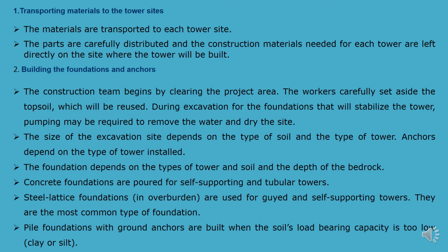The size of the excavation site depends on the type of soil and type of the tower, right? So size of excavation, right? So we cannot decide the sizes arbitrarily, but we have to design according to which type of soil is there and which type of tower is there, right? So according to that you have to decide the size of the foundations or excavation. Anchors depend on the type of tower installed. So anchoring, we have to use some anchoring system also, that depends upon the tower system.